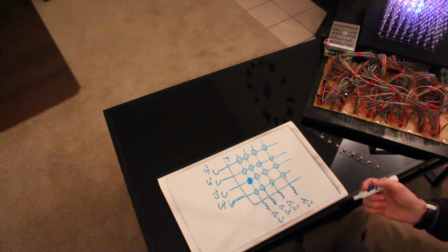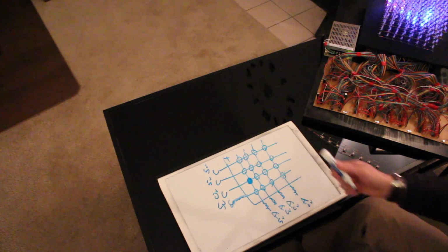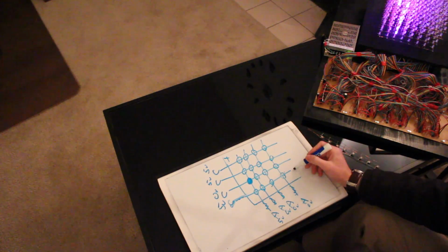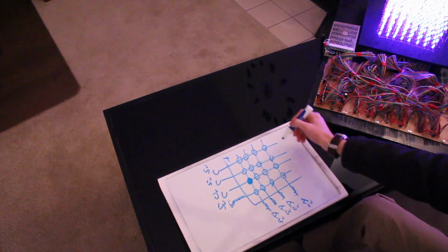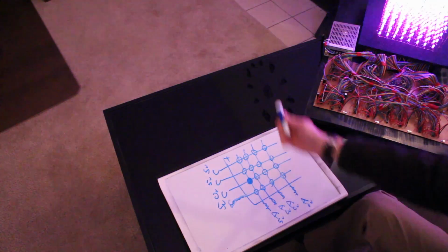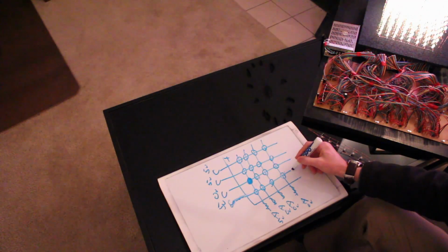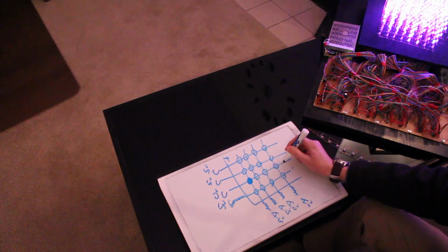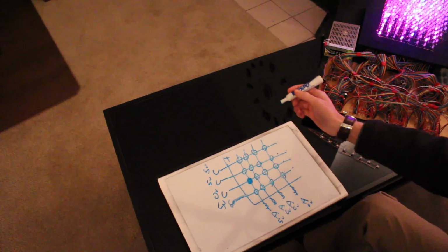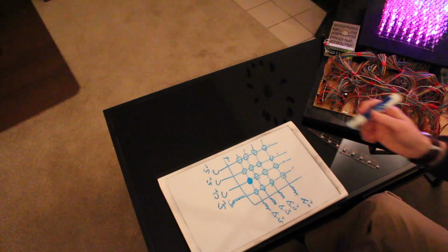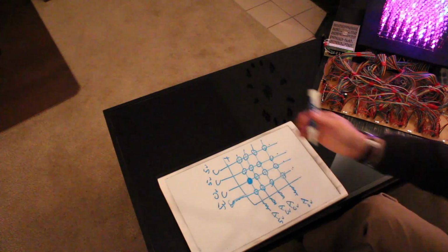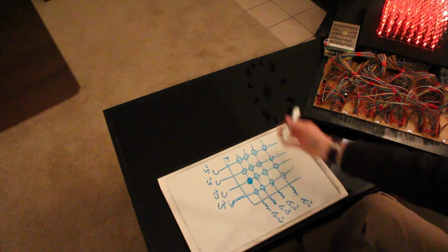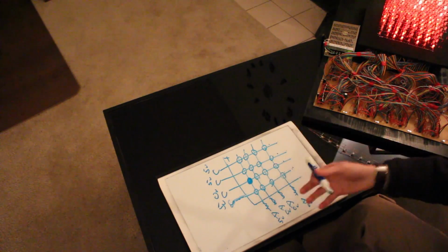But in practice, it's not modulating, it's more of a multiplexing type of scheme. So each row would have a chance to light up its LEDs. That's how your control scheme would work. You would let this first row light up for a period of time, then you turn it off. Let this one light up, turn it off. This one, turn it off. This one, turn it off. So you give each one a chance to light up. And you do that so quickly that, again, these are turning on and off, but you do it so quickly that you can't tell. And you repeat that.